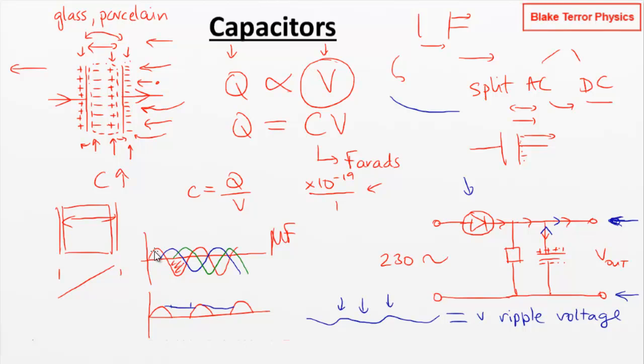You can see this is already smoothing it out quite a lot more, because when the capacitor is filling the gaps, it's not dropping off as much because it's only having to fill in for a shorter amount of time. So now our ripple is much smaller. You're still going to have a small ripple, but it's going to be fluctuating much more quickly and over a smaller range.